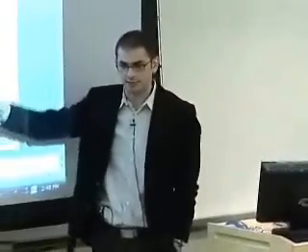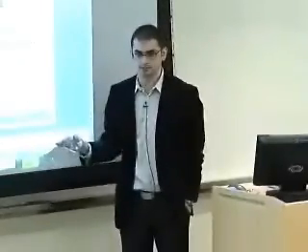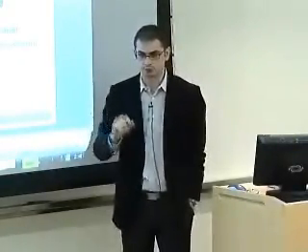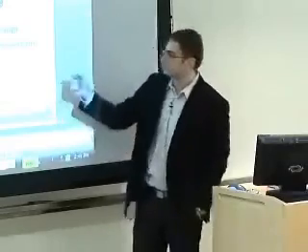Now, these cameras are totally different from the cameras you know. With CMOS cameras, you have to go to the camera, get images, and process the images to find events of interest. Now, these cameras have all the processing you need in the pixel, on a per-pixel basis. Every pixel operates independently of every other pixel. You design this pixel to detect a specific feature, for instance motion, edge, or something else. Whenever an event is detected in a pixel, an interrupt is given to your processor saying that this event occurred.